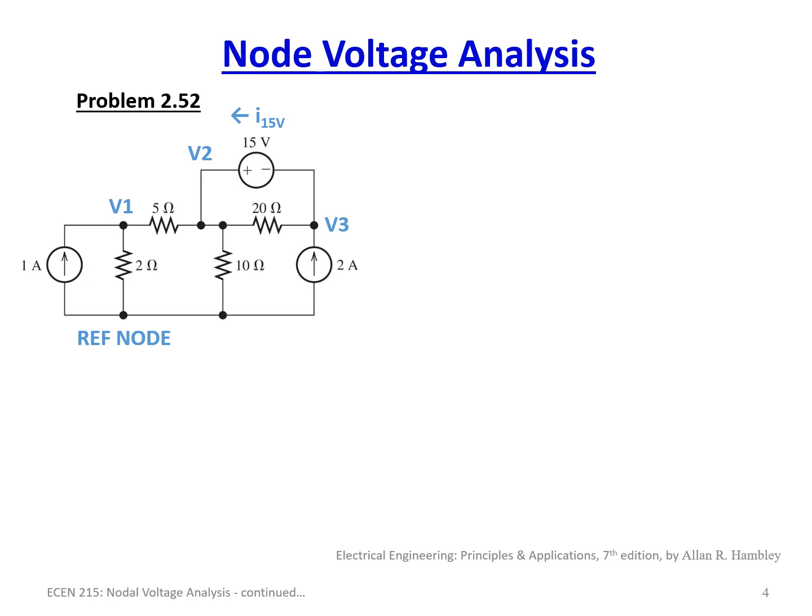So got the problem here. So let's write our first equation for V1. That's pretty straightforward. V1 over this 2 ohm resistor, so that is the current that is going through here. V1 minus V2 over 5 ohms, that is this current here going this way. I'll draw it a little cleaner for you.